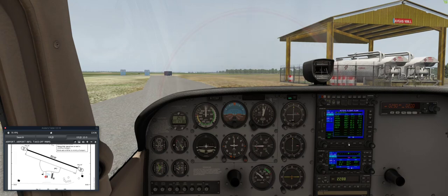And how do you get back out to the map? Well, if you're in the flight plan mode, because you hit the FPL button, you hit the FPL button again. If you're in VNAV mode, then you hit VNAV again to get out of that. If you're in procedures mode, you hit the proc button to get out of that. If you happen to have had 3 of them active, you've got to get out of a couple of them at least. That's just a little bit of basics of how to navigate the system.